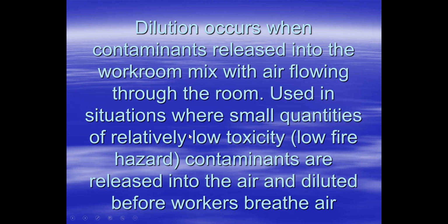I've got to stick with those relatively low toxicity, relatively low fire hazard contaminants, because by definition, it's being mixed and my worker is going to get a certain degree of exposure. I don't want to expose him to something that has a highly toxic or even moderately high toxic property, because I don't want him to, over time, start showing health effects from that chronic exposure.